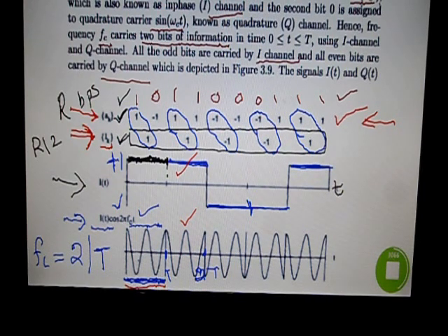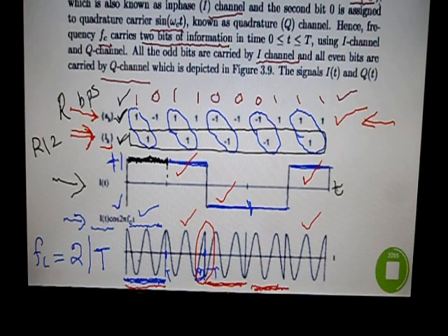In the third, the cos is multiplied with a negative, minus 1, so you can see a phase transition at instant 2t, after the second time interval. This is due to the negative polarity, the product of minus 1 and cos of 2 pi f ct. Similarly, minus 1 with cos of 2 pi f ct gives this waveform, and a positive one gives this waveform.